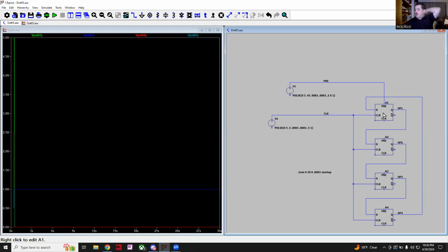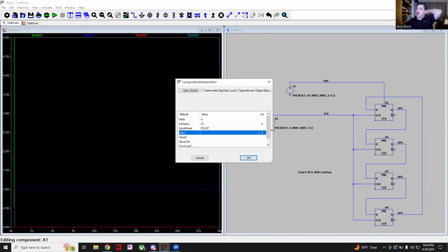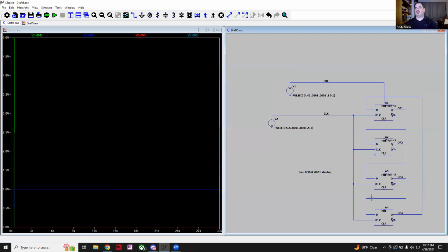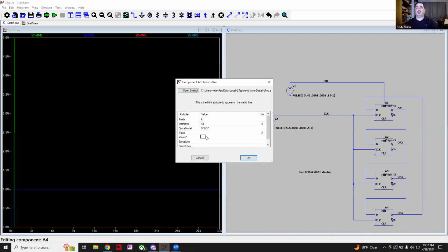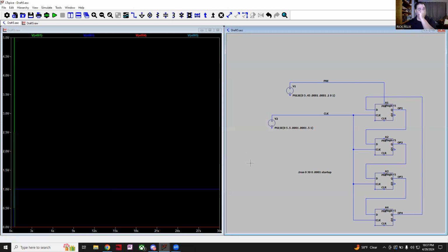And then the other thing that we didn't do was we needed to set the output voltage of the integrated circuit. To do that, there's a function called V high, and we will set V high to be equal to 5. So we'll copy that because we're going to need to do that on all of them. I didn't find a way to copy these settings easily from one value to another, but this program looks like it's pretty old. So features like that, I'm sure, are not available.